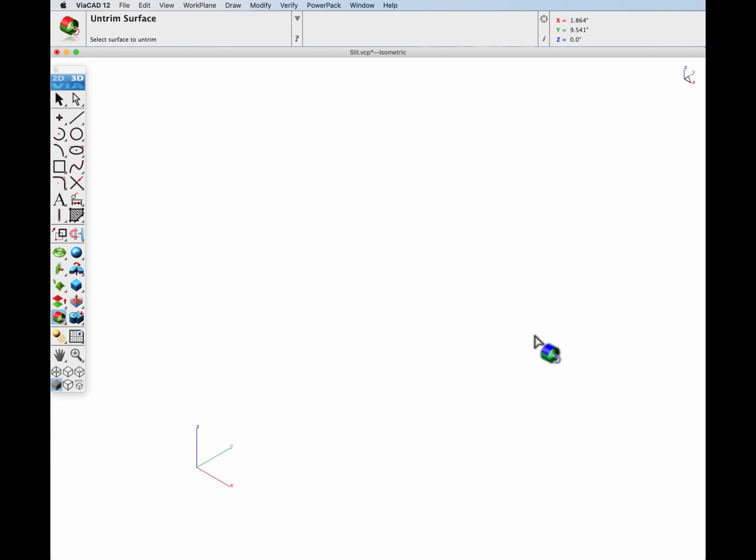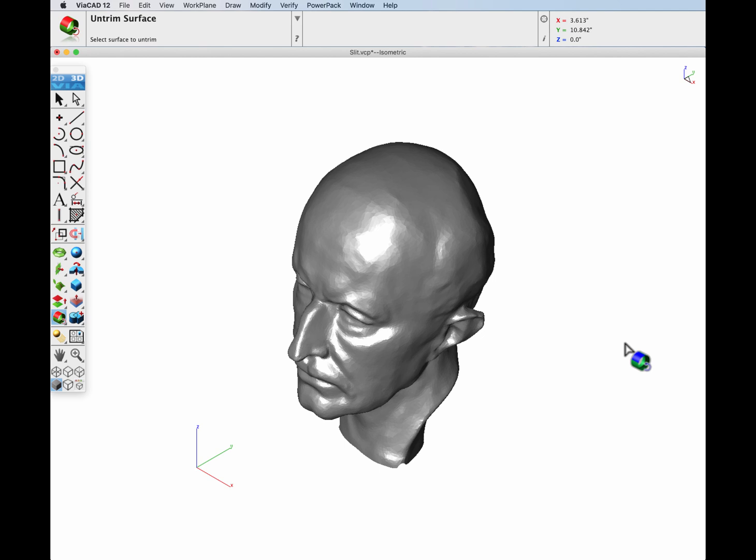The split mesh tool is particularly useful when creating parts for 3D printing. By splitting a part into smaller pieces, you can utilize smaller print tables. In this example, we'll split our part into two, add some alignment pegs using Booleans, and place on a printer bed. Let's display our 3D print tools